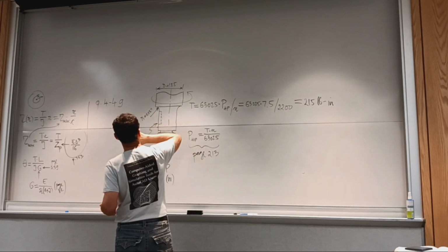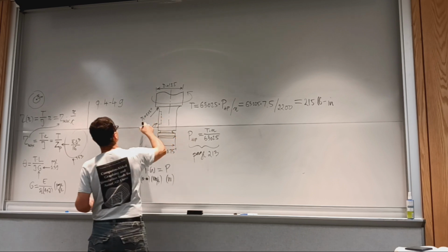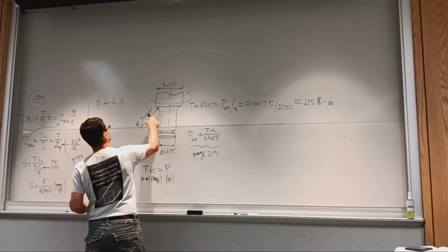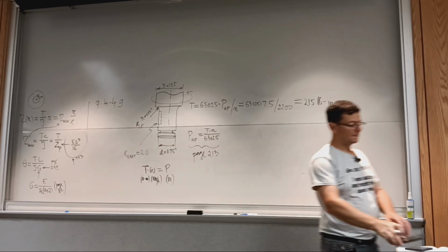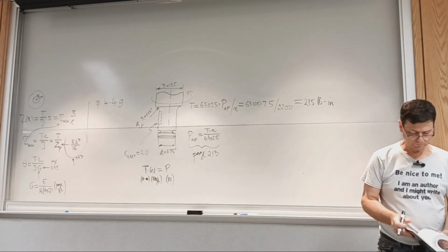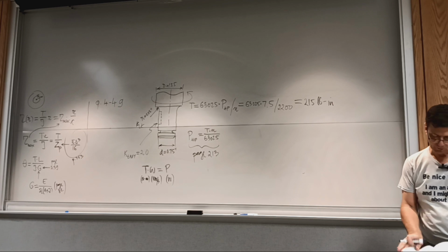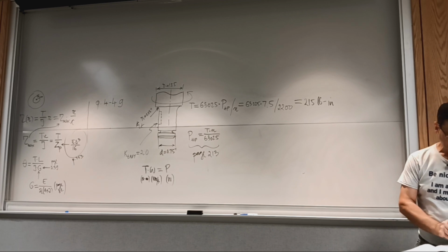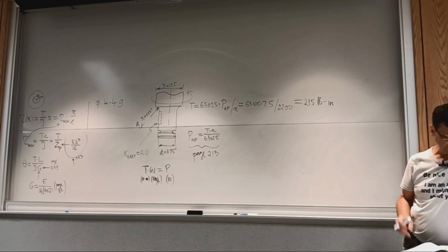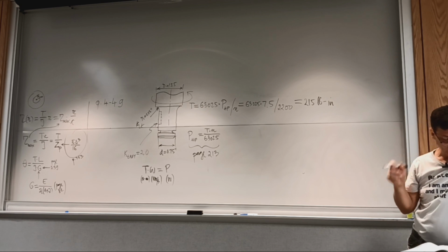Next would be to calculate or find, this one is clear, stress concentration factor here at the step. And for that, we go to the right appendix. I think we've been there before. And no, we analyzed one with a hole that had a common chart for axial torsion and bending.